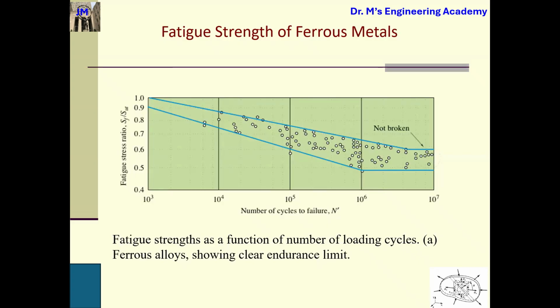For axial loading, S_E prime equals 0.45 S_U and S_L prime equals 0.75 S_U. For torsion, S_E prime equals 0.29 S_U and S_L prime equals 0.72 S_U.